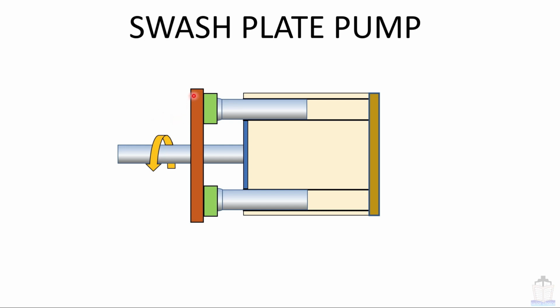So this is the swash plate cam, and this is the plunger, and these are barrels. When this cam is at 0 degree angle, then there is no pressure buildup, and when it moves to 15 degree angle, then hydraulic oil pressure builds up. So now you can see with the help of animation.